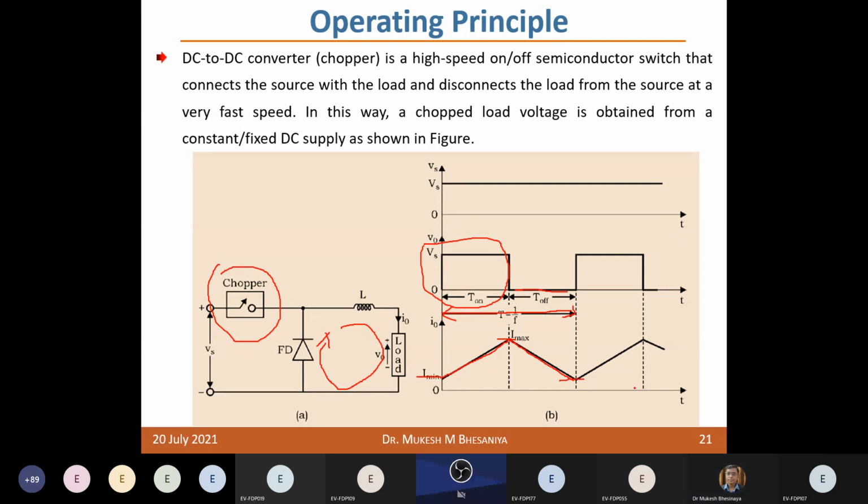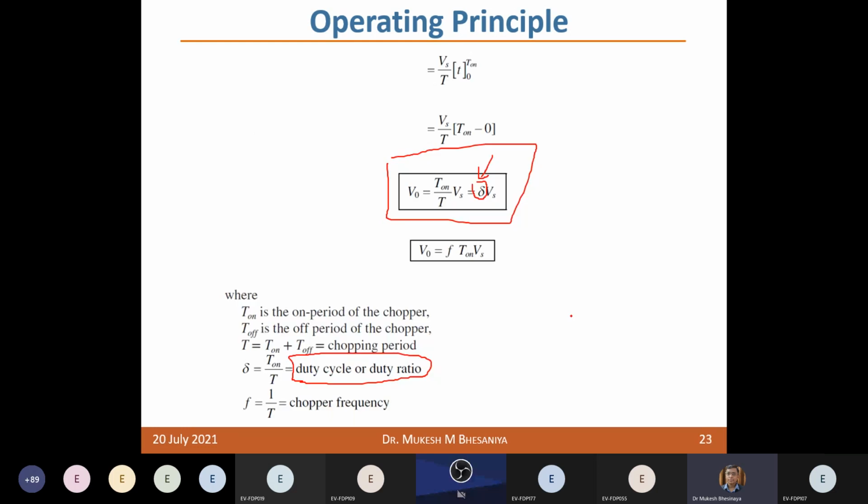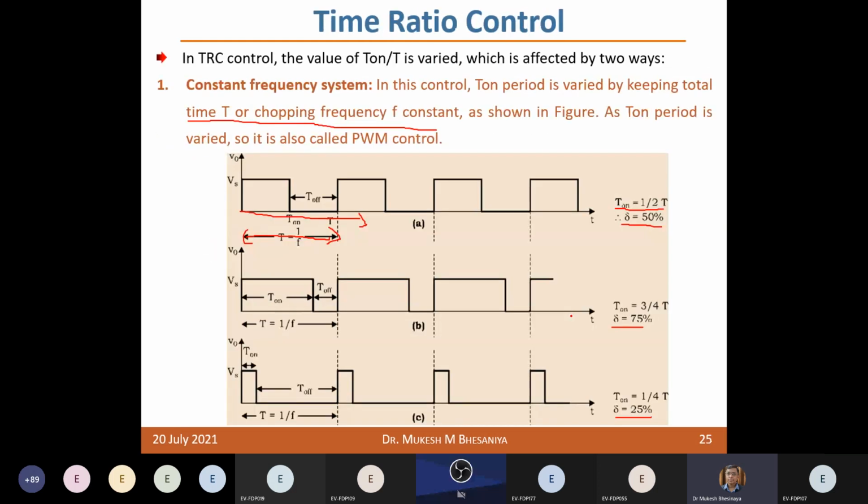Okay, so when you turn off the switch, your current will reduce and it goes down to this I minimum. Right. Now if you keep this switch off for a longer period, then whatever energy is stored in the inductor will be completely dissipated. And if it is completely dissipated, it will touch this x-axis, that is the zero line. Okay. So when all the energy stored in the load is dissipated, there is no current. It will reach 0. So this mode of operation is known as a discontinuous conduction mode. Right. So you need to consider all these aspects while designing the components for the converter, right?